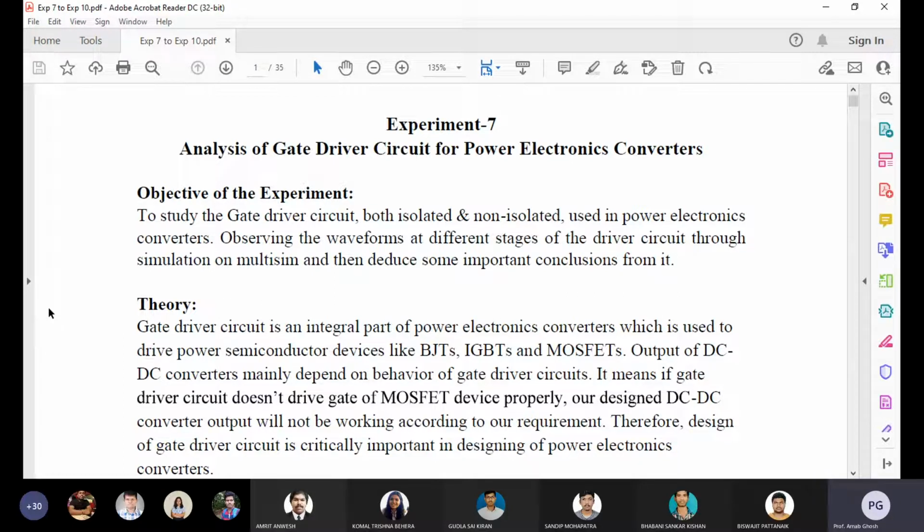What happens if any fault occurs in your power circuit? I am taking a MOSFET as an example, though in the case of IGCT it is also the emitter terminal. For high power applications with the MOSFET, we use a common terminal: the gate ground is directly connected to the source, and the gate driver's pulse terminal is directly connected to the gate of the control switch.